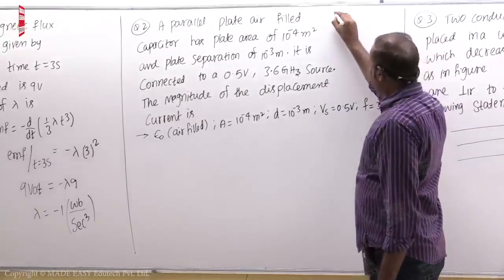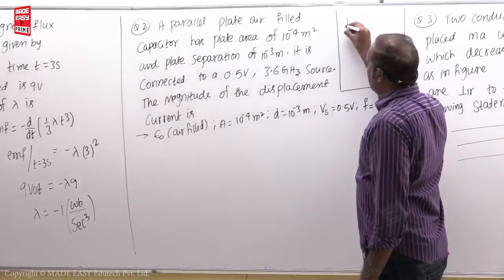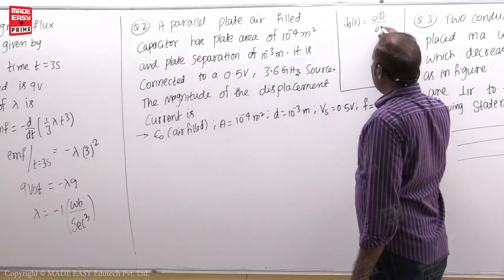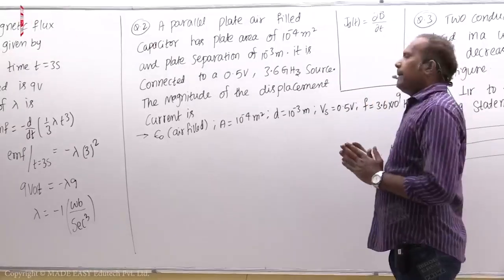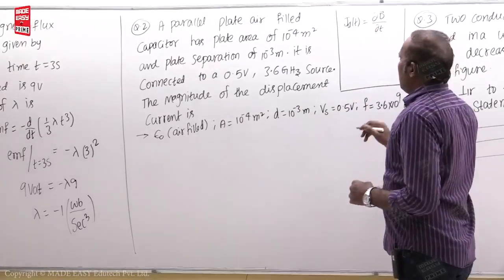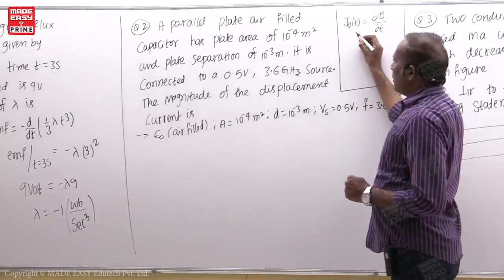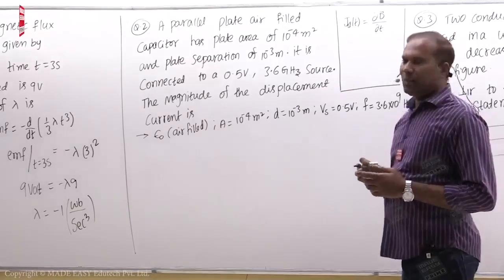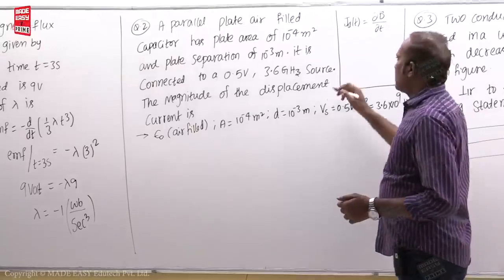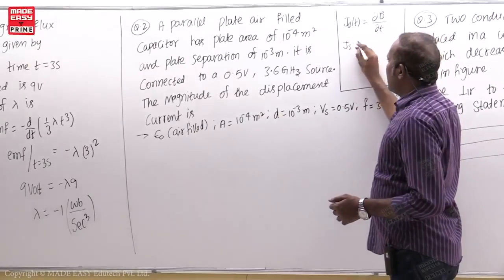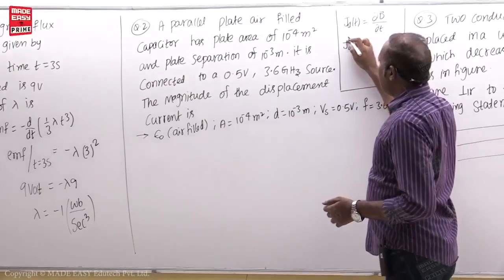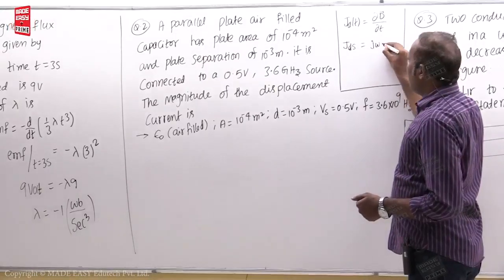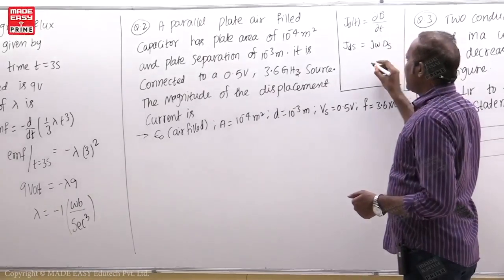So dear students, actually already you know two formulas, JD of t is equal to dou D bar divided by dou t. Actually it is in time domain. Now whenever frequency is given in the question, you have to write that in frequency domain or otherwise in steady state domain. So that is like network theory concept. So in steady state domain we will write this as JDS. S stands for steady state or otherwise frequency domain. In steady state d by dt is replaced with j omega, D is written as DS. S stands for steady state here.